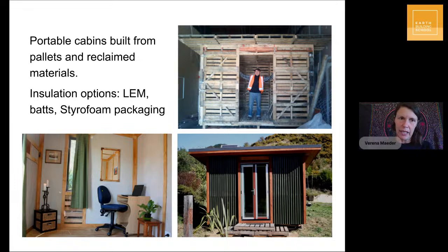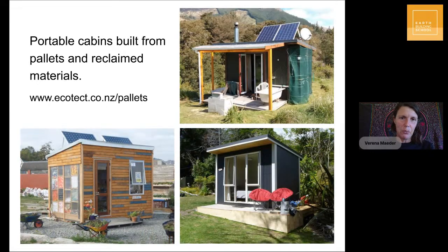We have used light earth infill in this system and much prefer it because of breathability considerations. And then the inside, to the bottom left, you see how he finished the inside. He used recycled carpet, has inside out with a clay paint. We have done the same, but instead of a clay paint, we have used earthen plaster to finish off this type of building. And it worked really well.